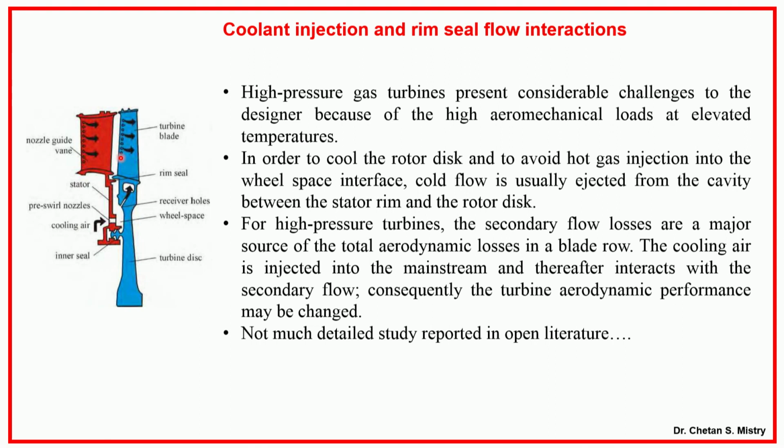Now the flow that will be coming out from this hole. We already have typically three-dimensional flow because of all this hodgepodge. Additionally, when the flow comes out from the stator or rotor blade, what will happen? It creates additional complexity in the flow, or it provides additional unsteadiness to the flow.